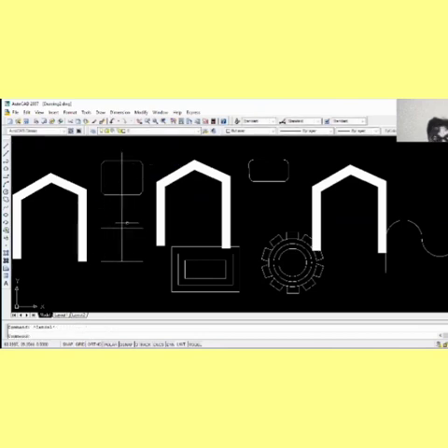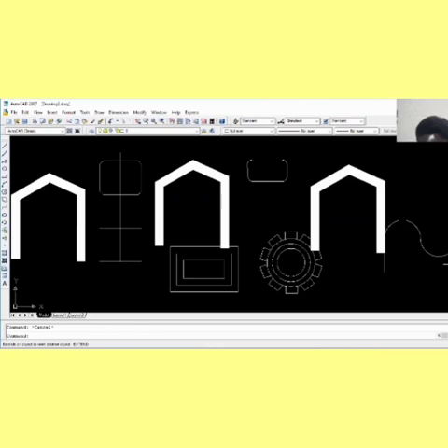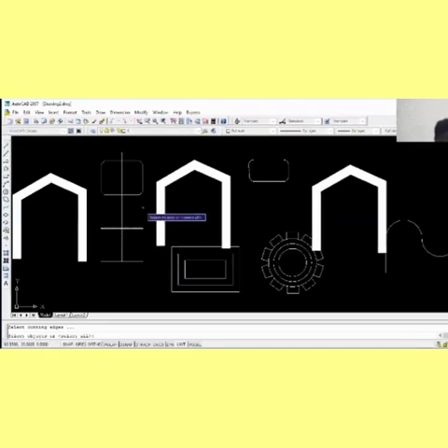So now, let's take a line, and let's draw it along this place. Assuming we don't want this part of the line, that's exactly when we use the trim command. You come in, click on this trim, then you right click, and then click on this place. You see that it has taken it out. If you don't want this place, you also come in, you chop it off like this. So that's exactly what your trim does.